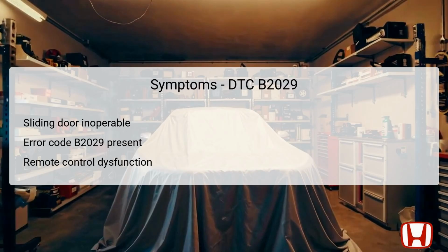The symptoms associated with DTC B2029 are primarily characterized by the inoperability of the left sliding door. Owners may notice that the door does not respond to commands from the remote control, indicating a failure in the system. Additionally, the presence of the specific error code B2029 during diagnostic scans further suggests a significant issue that needs addressing.